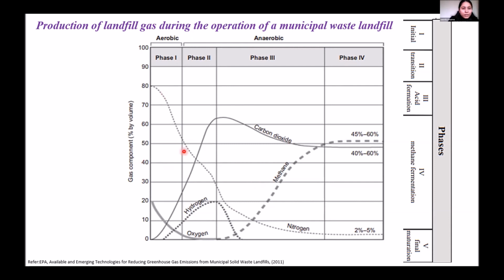I would not like to go into the details of all the phases, but there are some highlighting points I'd like to mention. Phase one is the state when the waste just enters the landfill. The moment the waste enters, there are a lot of voids in the waste, and a lot of molecular oxygen is available there. As a result, it gives an abundant opportunity for the microorganisms to grow. The density of the microorganisms increases, and they try to acclimatize to the changing scenario. Now, they take the oxygen and